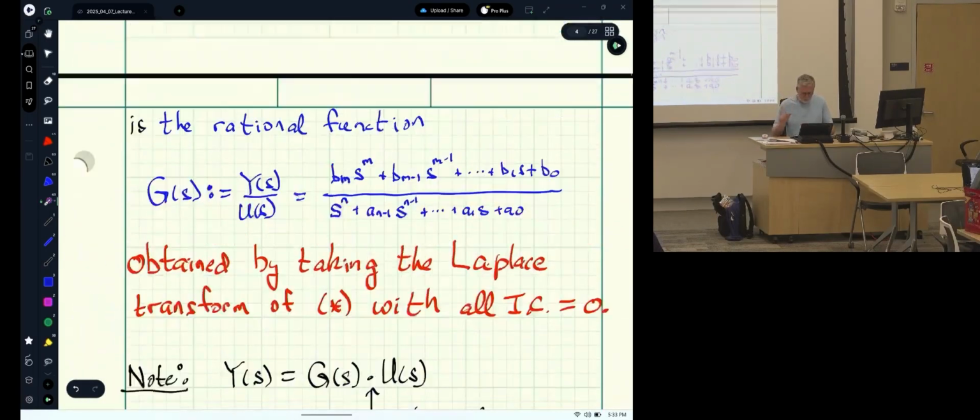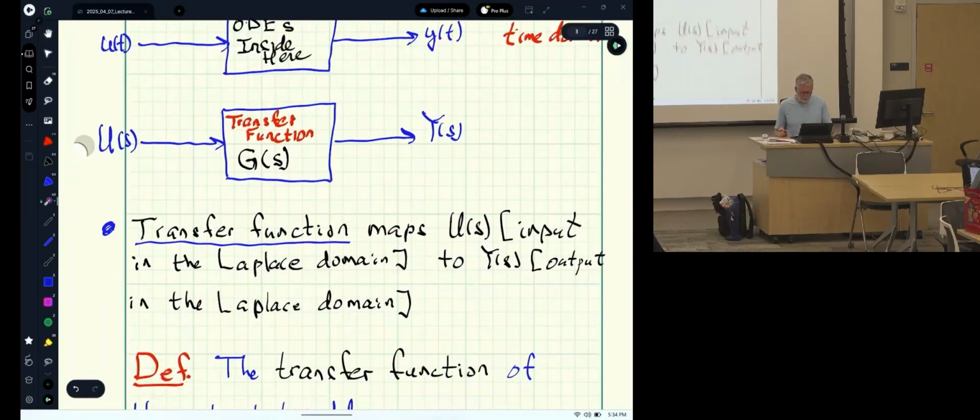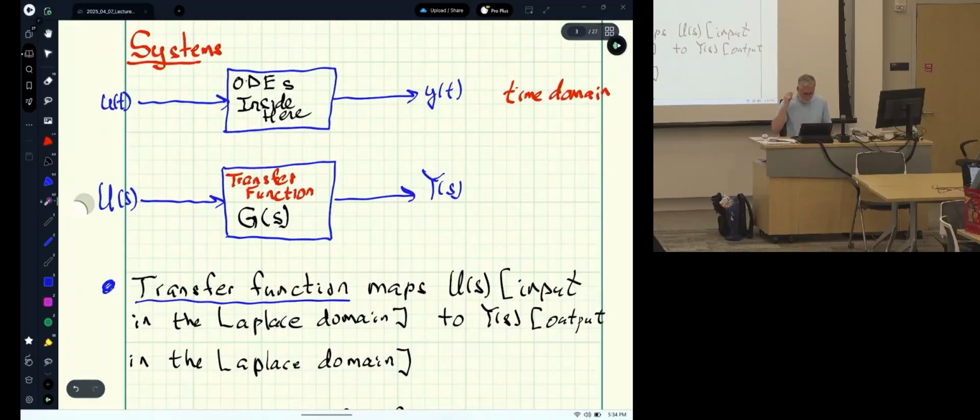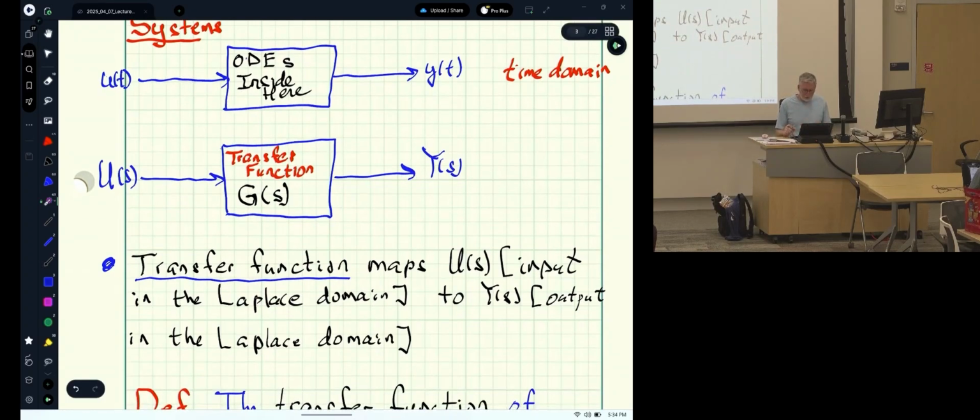Here's the conceptual part that we're moving into, systems. They're devices that are driven by input signals and produce output signals. So for the Segway, motor torque, good input signal, output signal, kind of your call. Lean angle, making that small, good signal. Speed, good signal.